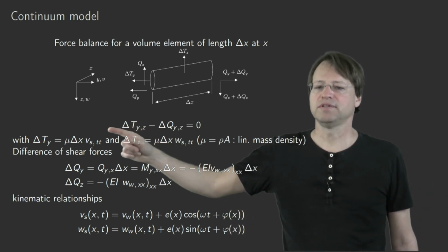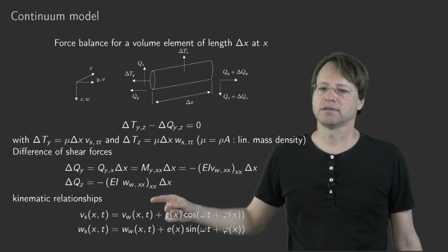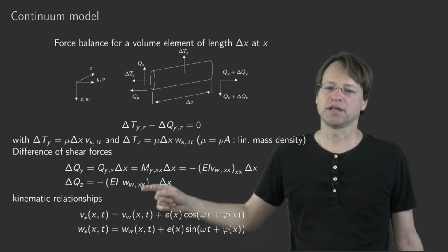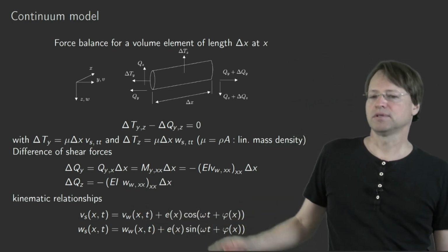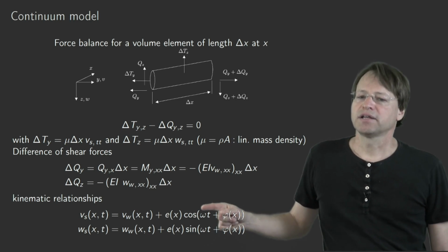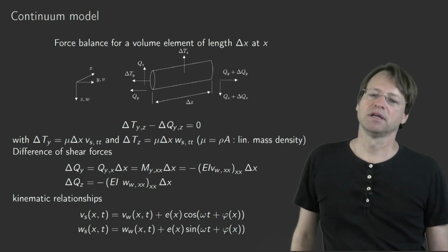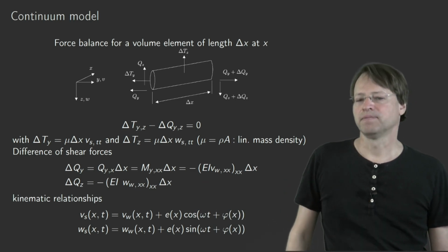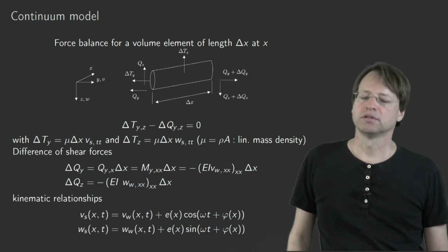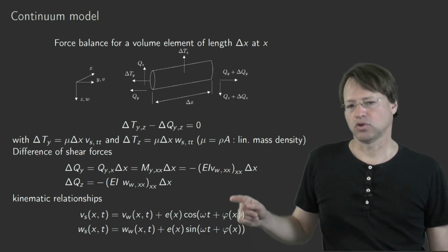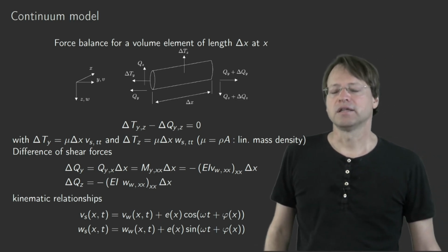And if we replace Vs by that expression for Vw, we see that we obtain the same as before, namely we have to take the second derivative of the coordinates with respect to w, and the second derivative of these cosine functions, because they are time dependent. And again, as we study only the stationary operation, we neglect terms in omega dot. So we get the same analogous forcing function on the right hand side than we had before.